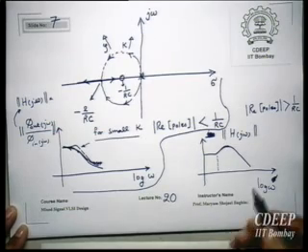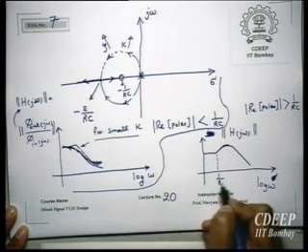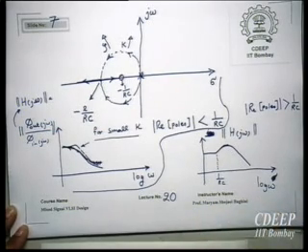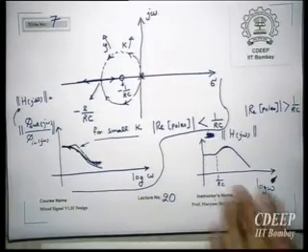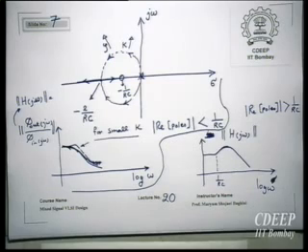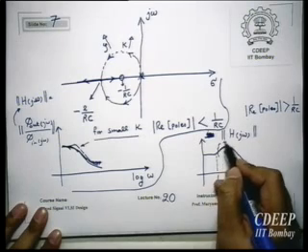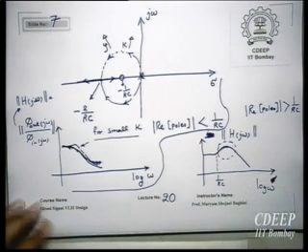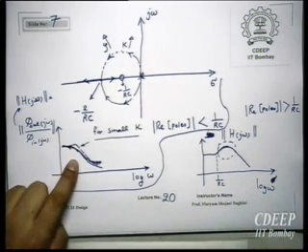Therefore, first we will see the effect of the 0. And then here you see you have a peaking. And this peaking actually will increase jitter. Therefore, the loop will behave as an amplifier for VCO jitter. That is a very important thing. We prefer to have this without any peaking.